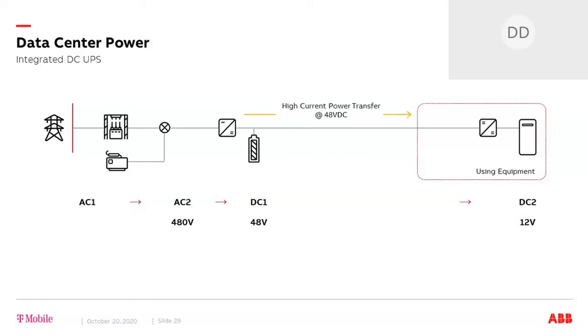As our power densities increased, we ran out of room to run the cables. 48-volt DC power distribution requires lots of large cables, so it makes sense to do the conversion to 48 volts closer to the loads.